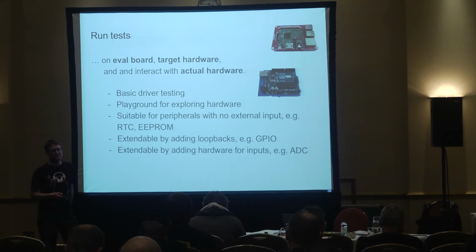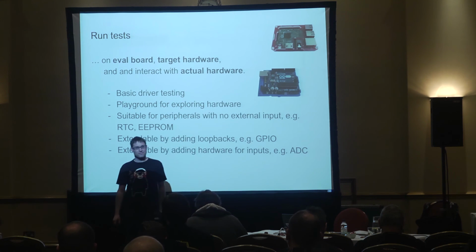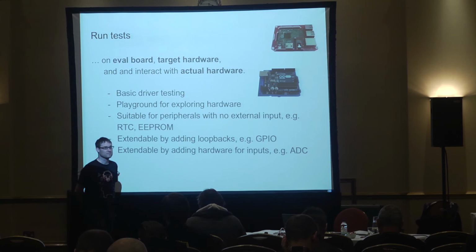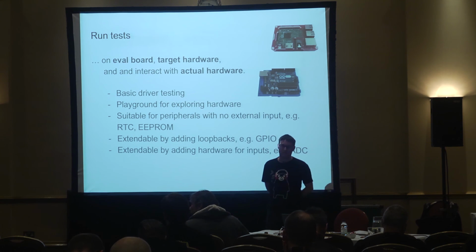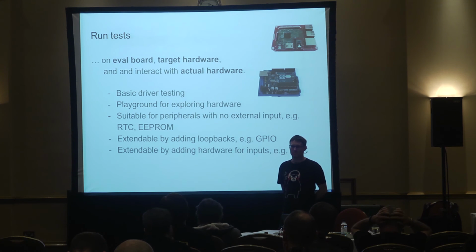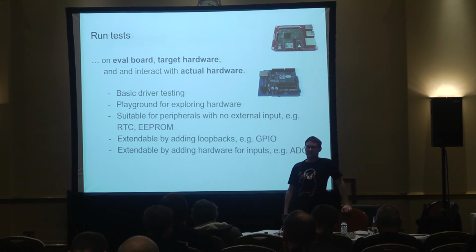So on one device I had to program a flash memory. The flash memory really is now quite sophisticated. It has some 7 commands for basic operations like read a block, write a block, flash a block, stuff like that. And that can be really tested anywhere but the hardware. But it has plenty of attached functionality like error correction logic, bad block handling, and stuff like that, which is quite opposite. You can't realistically try it on the chip because it will not generate bit errors where you want it and plenty of other stuff.